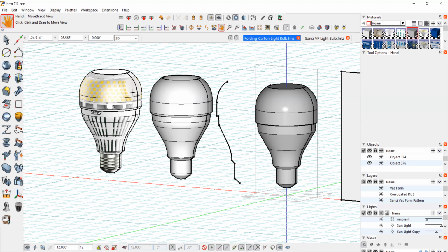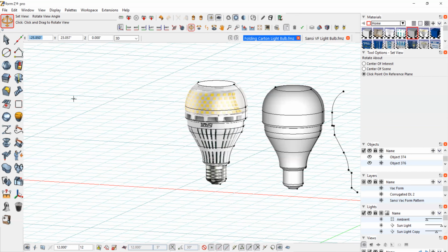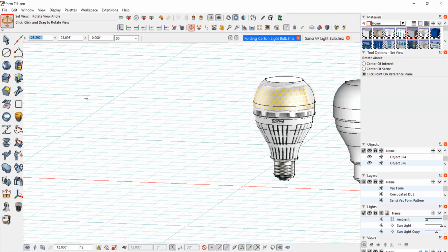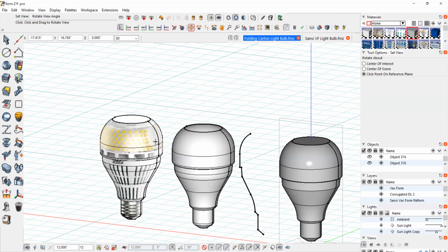You can map that right onto this geometry, and that's this other light bulb way on the left. So if you look at that from the front, and I'll do a rendering of it, it looks pretty good. But as you can see, as it comes around the corner, it's getting distorted because it's not UV mapped and it's just a flat photograph. It's not designed to be mapped around a dimensional object. It'll get distorted. But quite often, I'll just use this for rendering purposes.